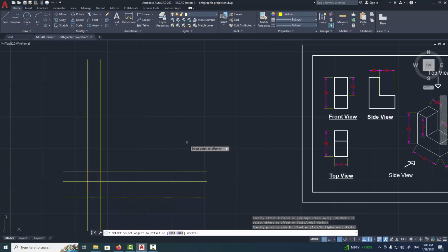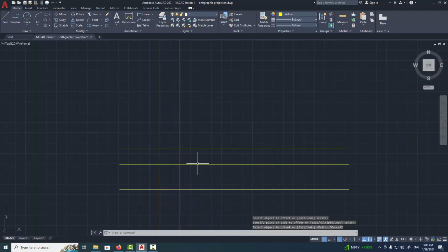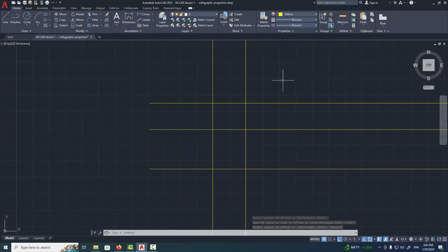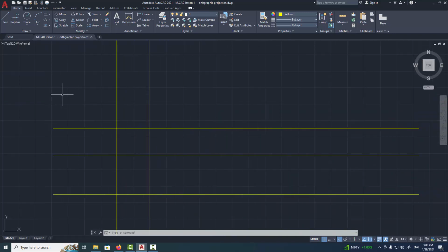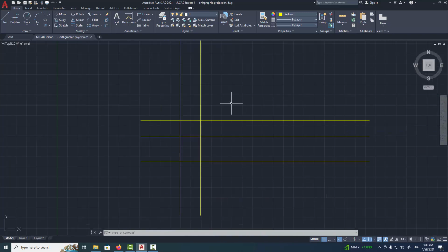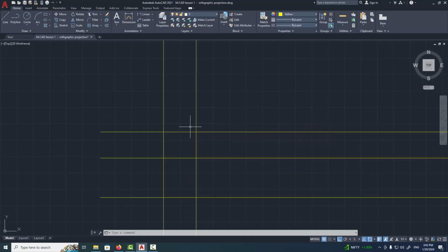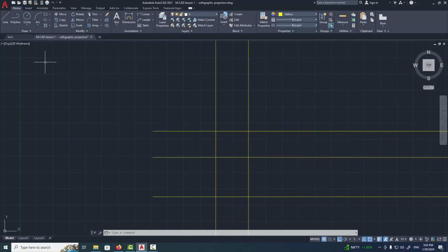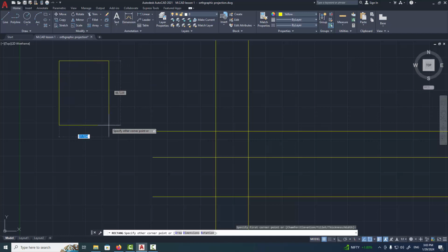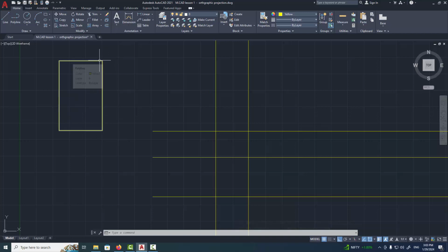Now as you can see, throughout the drawing process, I have been continuously using the navigation skills we've learned to maneuver through the drawing process. If you feel you are still not able to follow through, please go back and understand how it's done. I will select the rectangle tool to draw over the construction lines. When you select the tool, here it says specify the first corner. Click on the first corner, then drag and click on the second to create the rectangle. That's how we do it.